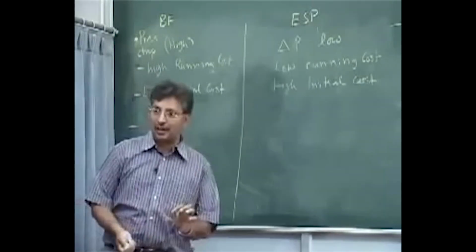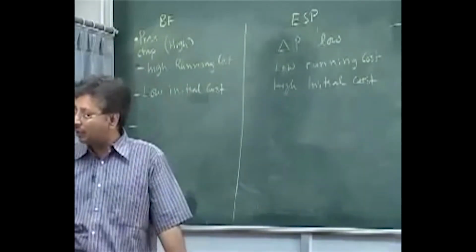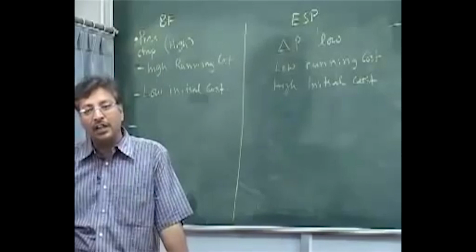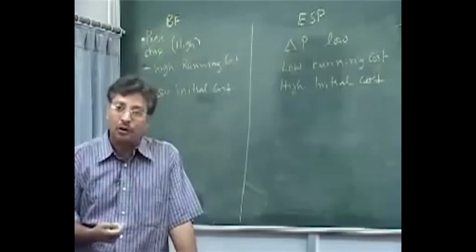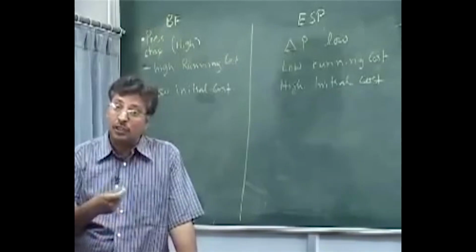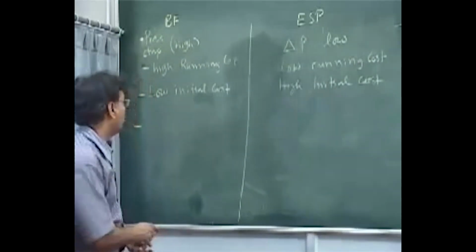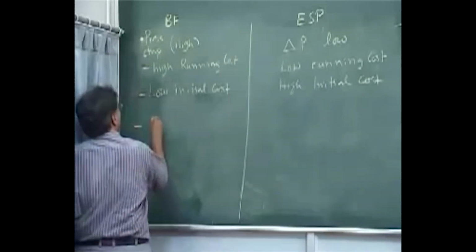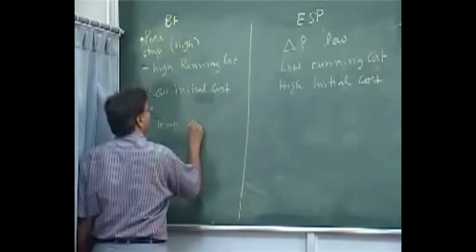Given the type of the bag and the temperature, can all bags or fabrics adjust to all temperatures? No. If the cotton is there, for example, and the heat is very high, it may not be able to adjust. So the bag filter is temperature sensitive.